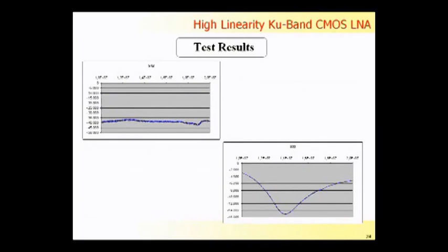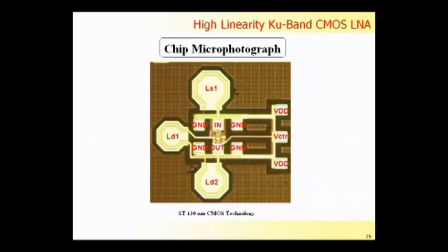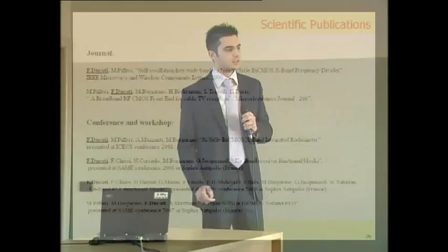Yes, the last two scattering parameters: S12 highlights that the output is well isolated from the input, and S22 shows that the output matching is also good. Here is the picture of the system. Here is the core of the LNA. Here is the pad ring that is put between the inductor and the core in order to minimize as much as possible the parasitic effects, and here is the inductor. It is my publication that I did during my PhD. I have finished. If there are any questions.